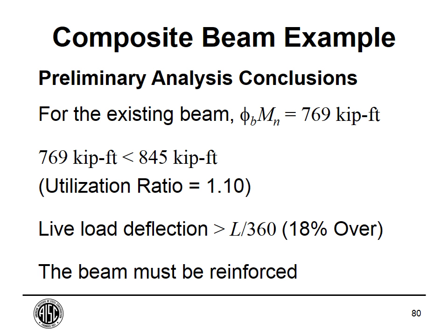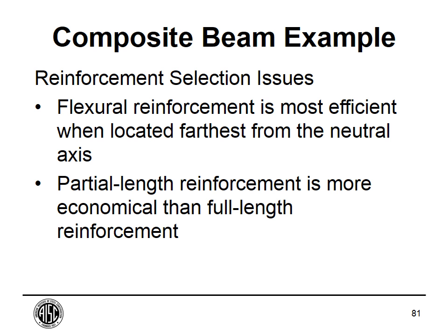So we know that our existing beam is only worth 769, so we're about 10% over. Additionally, we're over a little bit on the deflection too. So we're going to go ahead and add some reinforcement.